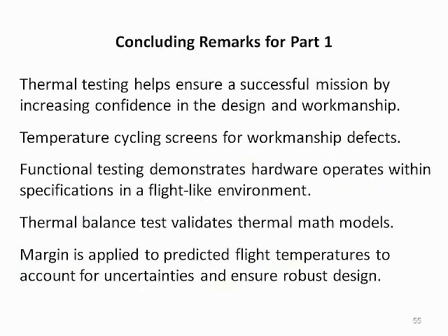There are several key takeaways from this first lesson. Overall, thermal testing helps ensure a successful mission by increasing confidence in the design and workmanship. Temperature cycling provides a screen for workmanship defects, while functional testing demonstrates that the hardware operates within specifications in a flight-like environment. Thermal balance testing validates thermal math models and increases confidence in the thermal design. We have also stressed the important role that margin plays in accounting for uncertainties and ensuring design robustness.